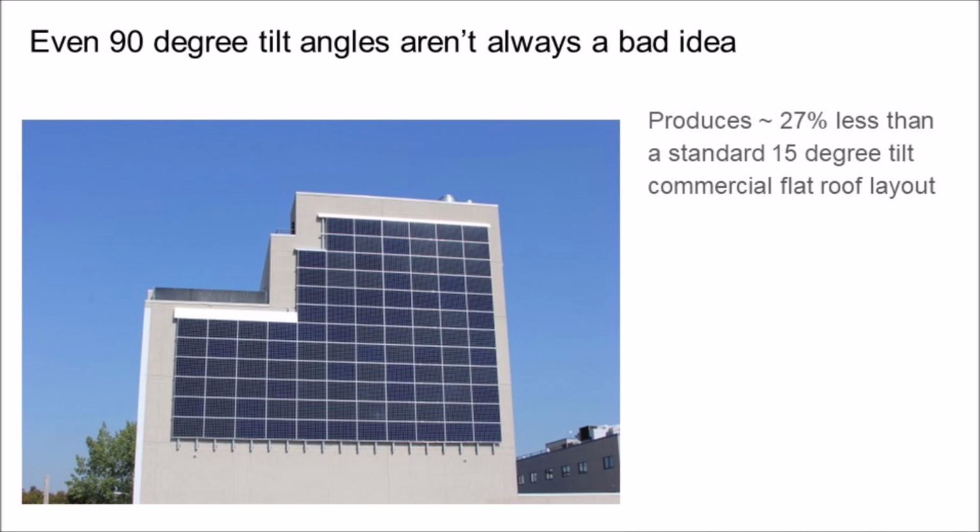So as far as roof tilt goes, the array will follow the roof. Tilting up off the roof rarely makes sense, especially when the structure is considered. Steep angles will increase solar production, but also increase the installation and operating cost of the system, as the roof will no longer be walkable.